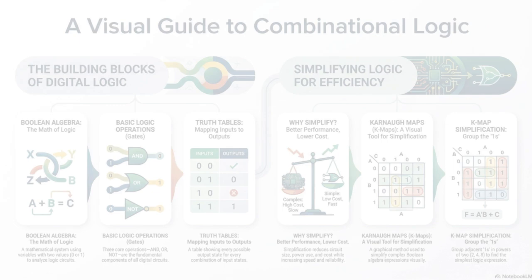It's wild to think that a pencil and paper exercise translates directly to billions of dollars saved and microseconds gained in hardware. It really does. Take a simple expression like X plus overline X Y. Okay. Using a basic Boolean theorem, that entire function simplifies to just X plus Y. Wow. So think about the hardware. The original version needed an inverter for the overline, an AND gate, and then an OR gate. 3 components. And the simplified one? Just a single OR gate. That one algebraic step removed 2 physical components and shortened the signal path. That's a huge deal. That's incredibly persuasive.